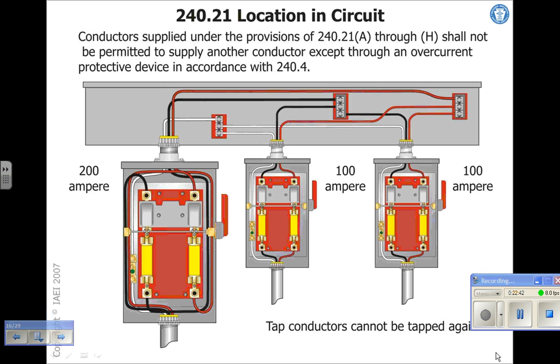Now this is what we're looking at. This is the beginning of our motor block information. We're looking at an auxiliary gutter here, and 3 fused disconnects, sometimes known as a safety switch, or other names. And here we have tap conductors. You see how these come up here, and the black feeder goes into all 3 disconnects? You see that? And it's not connected to any incoming power yet, is it?